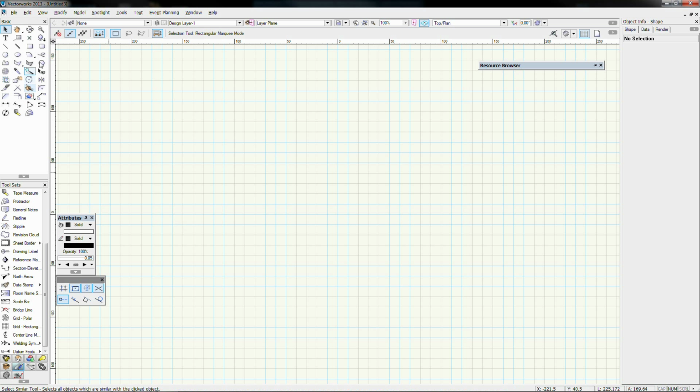Cool. So we're going to talk about a technique called lofting, and you might have heard me mention this in lesson 2, and we just touched on the 3D stuff going on in here. You'll find lofting inside here under loft surface. And what lofting does is it's kind of like one of those CAT scans that you see on the medical movies all the time, where they slice the brain and the skull up into several sections. This is the reverse of that, where you have several sections and you turn them into a 3D object.